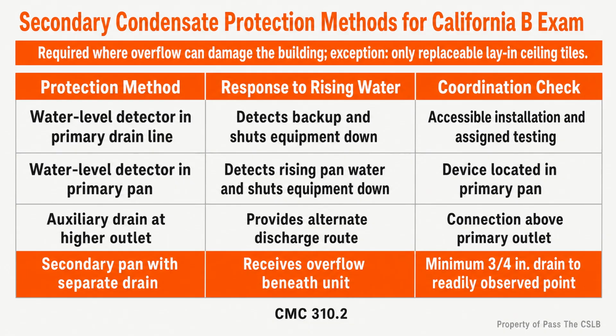Where attic equipment requires access, the opening must be at least 22 inches by 30 inches, or large enough to remove the largest single component of the appliance, whichever requires more space. The second part prevents the minimum opening from becoming an excuse for trapping a major component permanently in the attic.